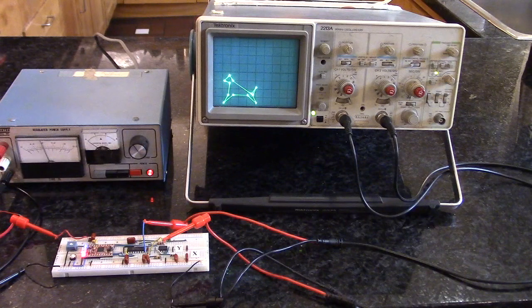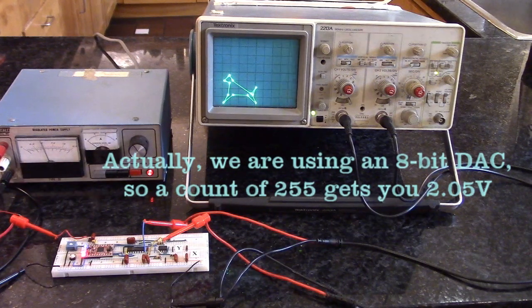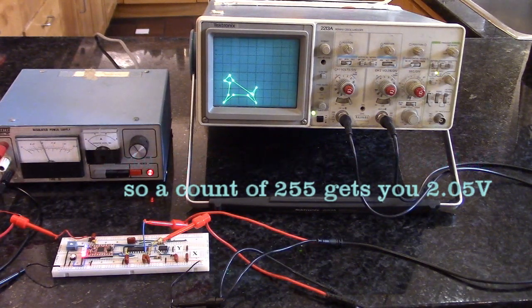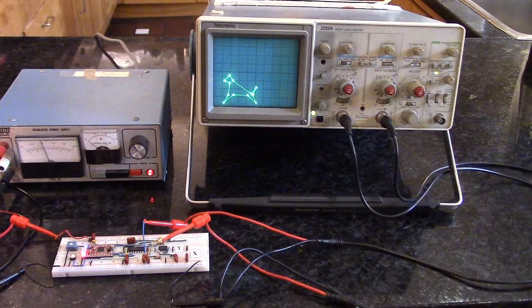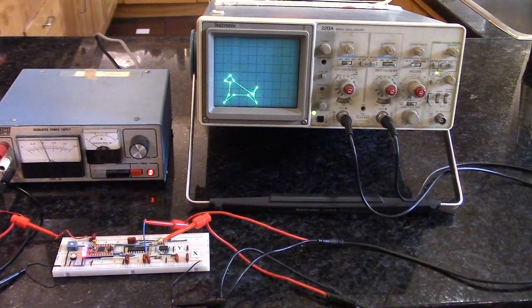If the reference is 2 volts, your output goes from 0 to 2 volts max with the largest count. In this case, I think we're using a 10-bit DAC, so that means a count of 1023 gets you 2 volts. And if you put a reference of 3.3 volts, which is the one we're going to be using in the next demonstration, you go 0 to 3.3 volts.